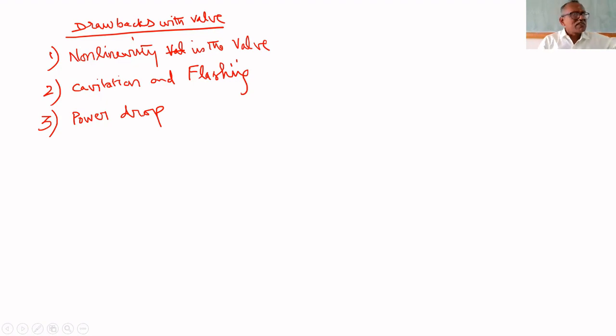Flow rate is a function of upstream pressure as well as density. If upstream pressure changes, flow rate may change. Suppose upstream pressure decreases. You opened 100% for 5 feet. Upstream pressure decreases, flow rate will decrease. But valve opening is how much? 100%. You can't open beyond 100%. You cannot adjust, you cannot control. That's why the nominal value must be 50%. If you want to open more, there must be a provision to open further.